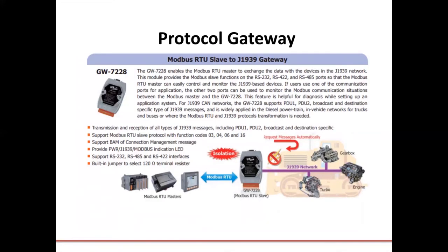Protocol gateways are very useful for large data acquisition systems. If you have existing devices like PLCs, HMIs, or sensors that communicate using different protocols, like for instance, if you're going to a SCADA system, you want to incorporate everything into a single driver or single communication type to make it easier, protocol gateways are oftentimes a very simple and economical solution.